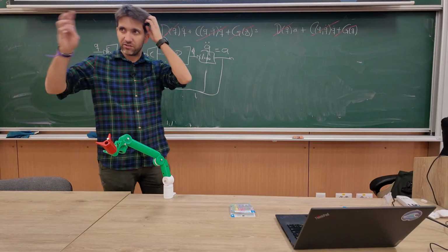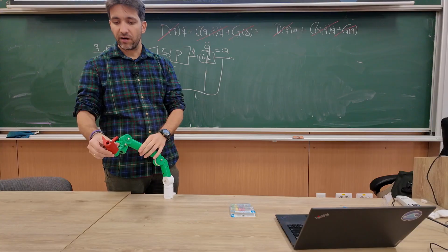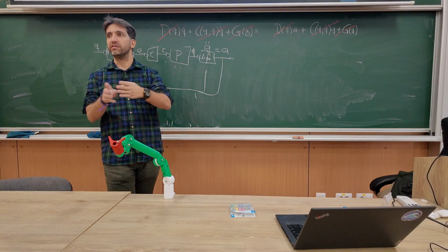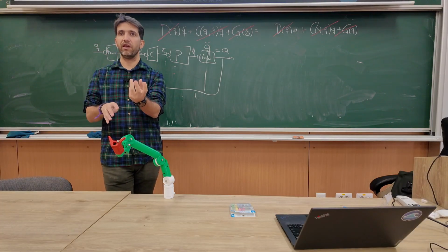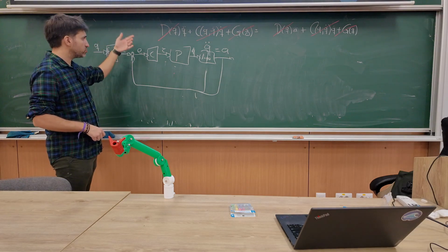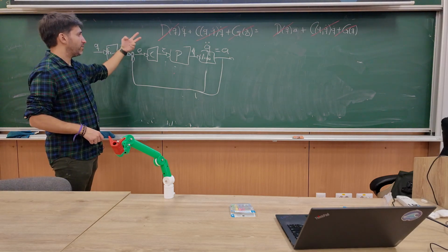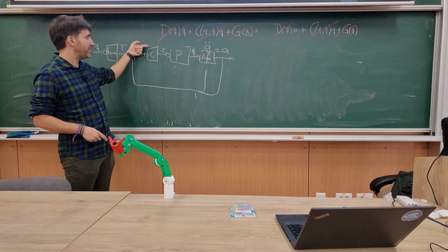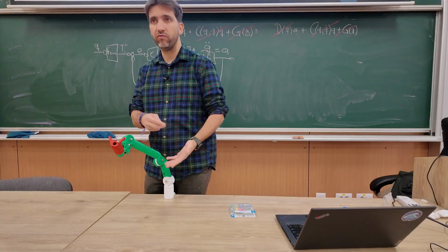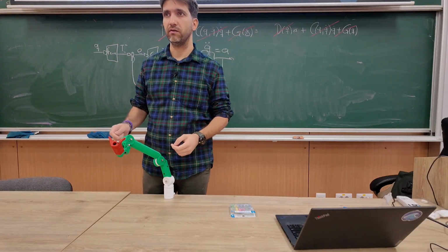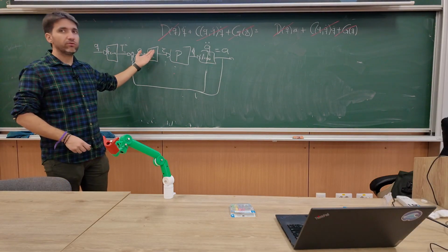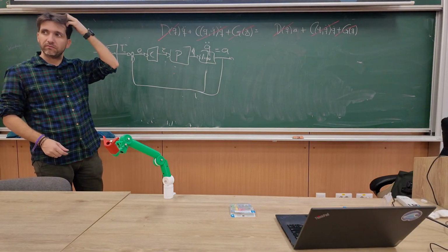Because let's say we have a target position here and we are a bit to the left. So we have basically a difference on the X axis. Everything else is okay, but we need to go a bit to the right, okay? So all the errors will be 0, and I will have 1, 0 that is 1, right? I have to decompose that error and figure out what joint has to move in what way to move a bit to the right, right? So the controller cannot do that, right?